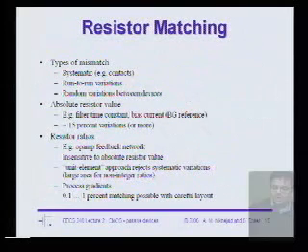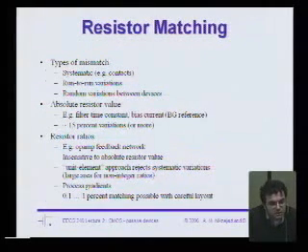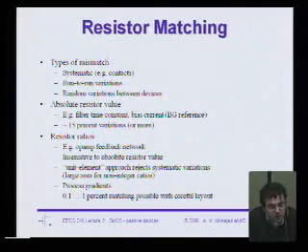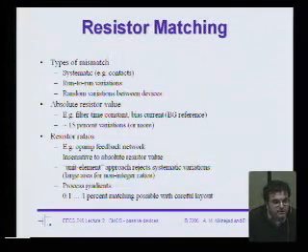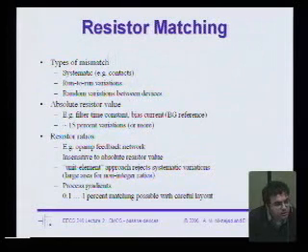Okay, the other important thing about analog circuits is matching. And the idea is that we're going to build circuits where, let's say we're using feedback. In an open loop circuit, let's say your gain is GM times RL. So you're actually sensitive to the absolute value of resistance. That's a really bad thing because the absolute value of resistance can vary a lot. Depending on the technology, it might be 30–40%. So your gain would vary 30–40%. So really what we do is we try to avoid circuits that rely on absolute value of resistances, right?